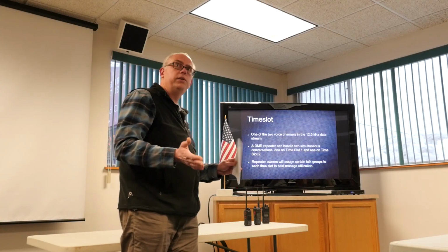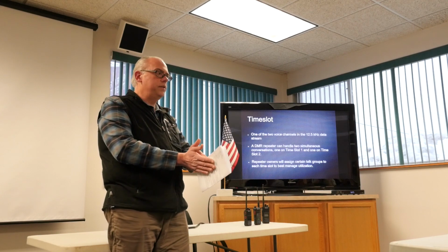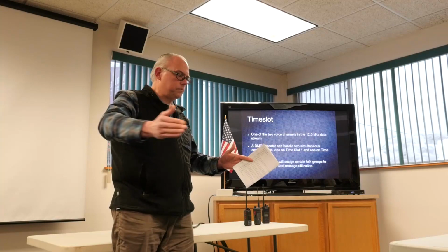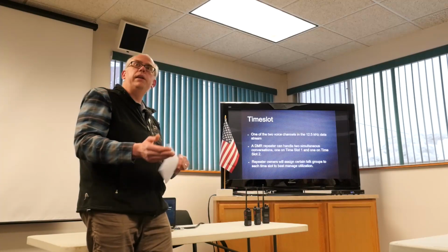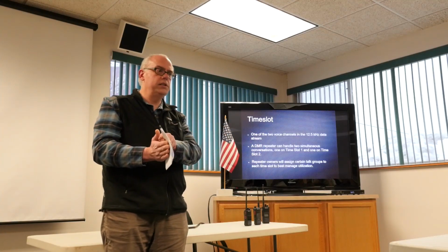Time slots. We talked a little bit about time slots. With your TDMA method of splitting your signal into two voice streams, each voice stream is referenced as a time slot. So your first voice channel is time slot 1, and your second one is time slot number 2. A DMR repeater can handle 2 simultaneous conversations, one on time slot 1 and one on time slot 2.